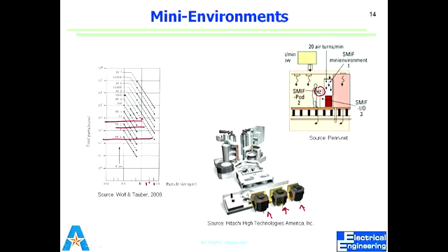In the clean room, maintaining that integrity is not always only the filtering, it's users' behavior also. It's not always just how good the equipment works, it's how good the users are. You'll see people doing stuff that you would want to pull your hair out over, and they'll be qualified and publishing papers, but you see their behavior in the clean room, they don't use common sense. So people are a major contributor to degrading the class, right?